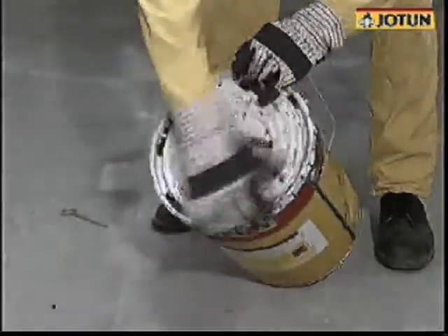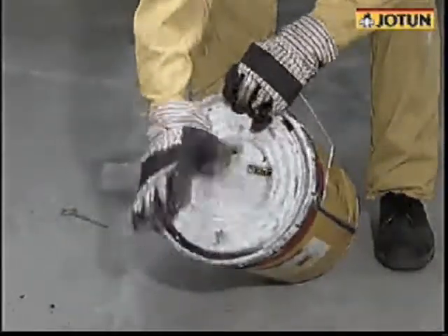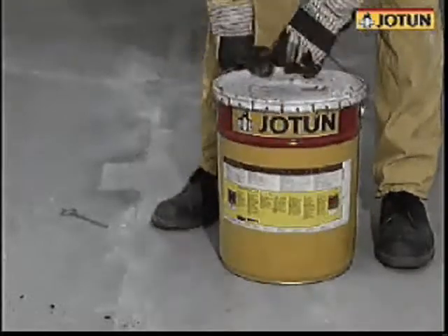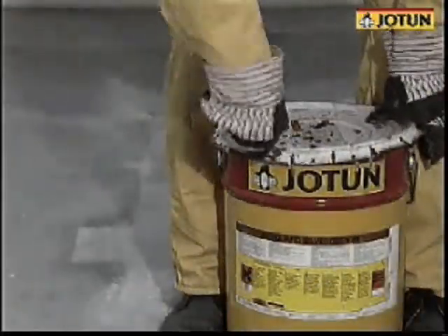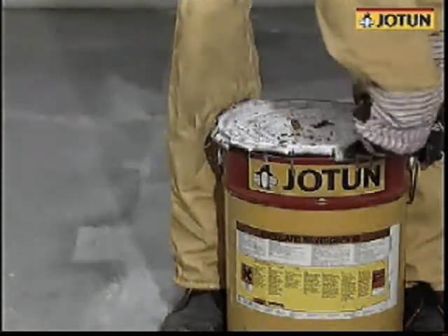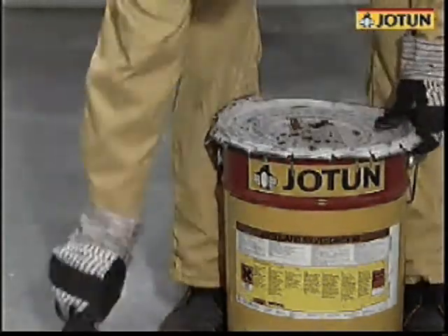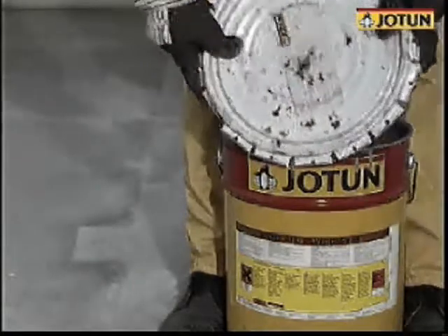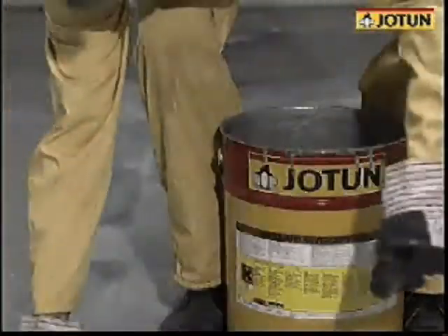Foreign matters on the lid of the paint tin must not fall into the paint. Spray nozzles are very sensitive to contamination, and problems with the application equipment will delay the work. The inspector may also reject a contaminated painted area, resulting in a time-consuming, costly reblasting.